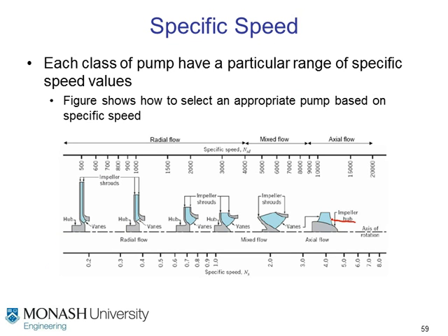Alright, axial flow, the flow go like this. Okay or not? Alright, this is the hub, this is the axis. Alright? But although it's spinning, it goes more or less axially like this. This one, the flow comes in and goes out like this. Alright or not? That's the centrifugal one. Comes in the center, spin, and then it goes up. Alright? Next one, there's a little bit of both. Bit of axial flow, bit of spinning, and goes out like this. Okay? So that's how you read this picture in the middle.